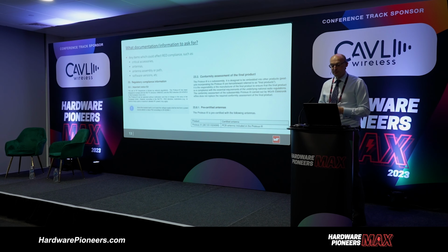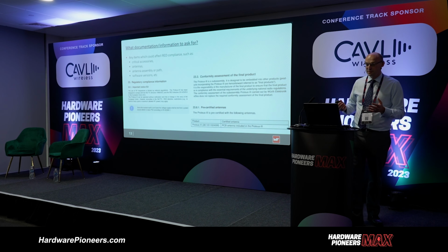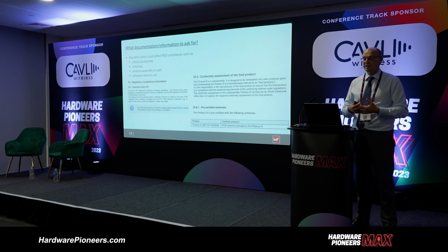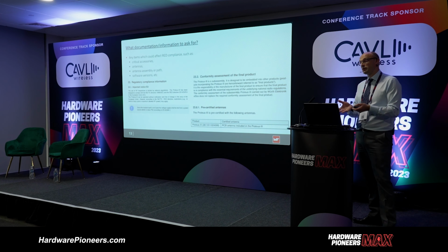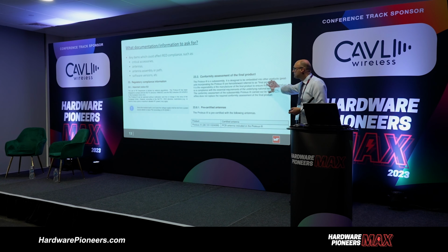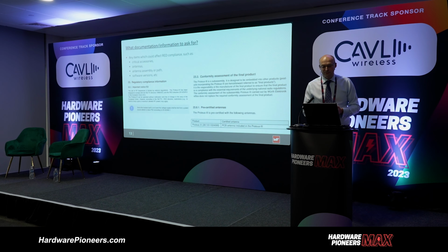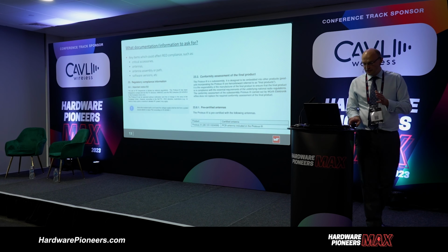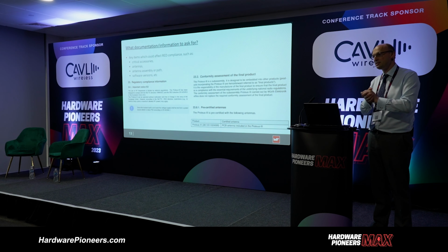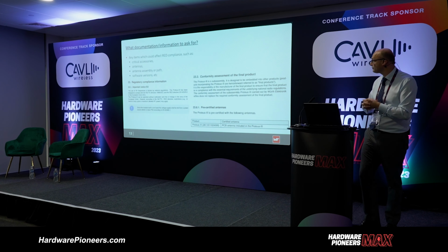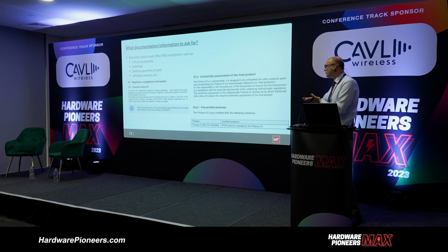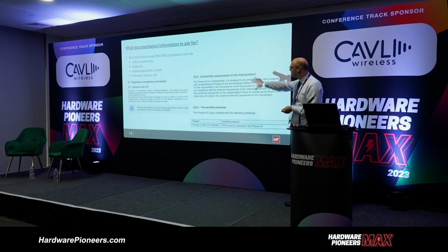So what other information may you need to consider? Well, as an RF module manufacturer, we also need to make you aware, as the end customer, of your obligations. Certainly, conformity assessment of the final product. When these modules are tested, they're normally tested on an eval board, so the actual certification itself is based on that eval board, with a couple of little power supplies to power the unit. So it is classed as a sub-assembly.